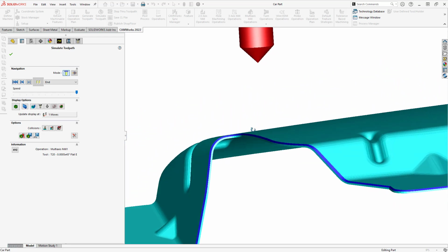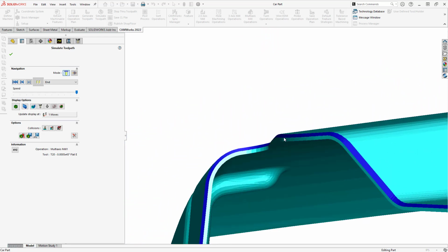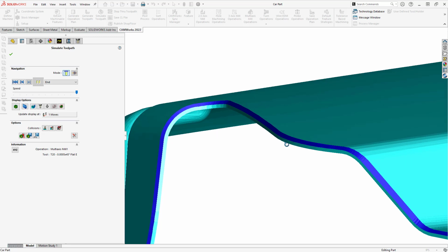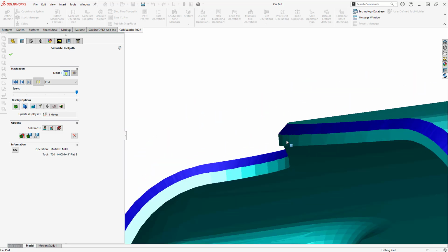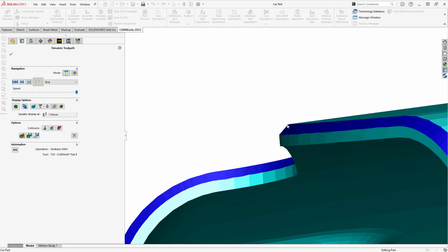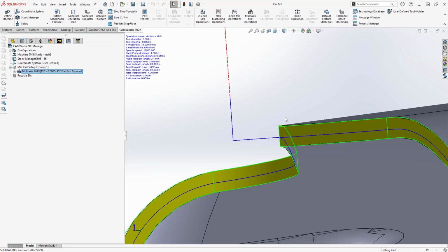And the reason I did 20 thou, probably not the best deburring chamfer, but I wanted to show it because I know the height of those sidewalls is about 40 thou. So we can just see that, yes, exactly, that looks like it's 45, and that is about 20 thou depth right there. So this is an easy way to get that 5-axis chamfer.